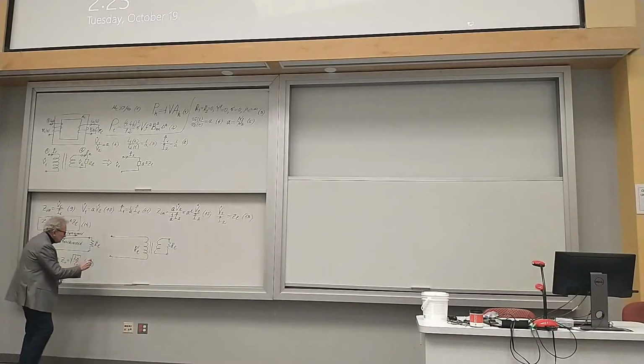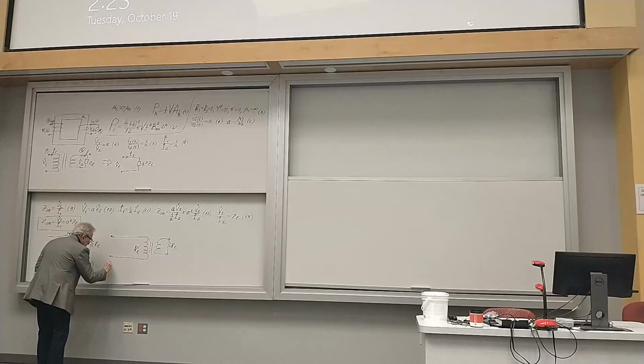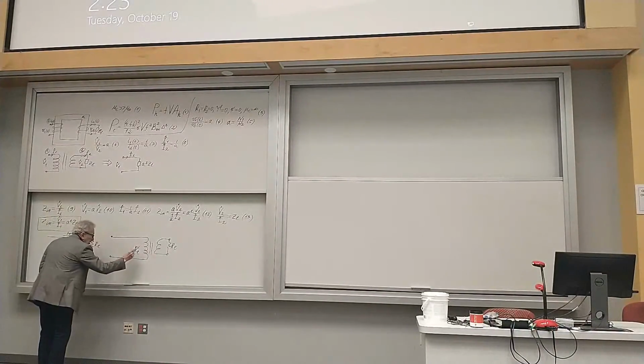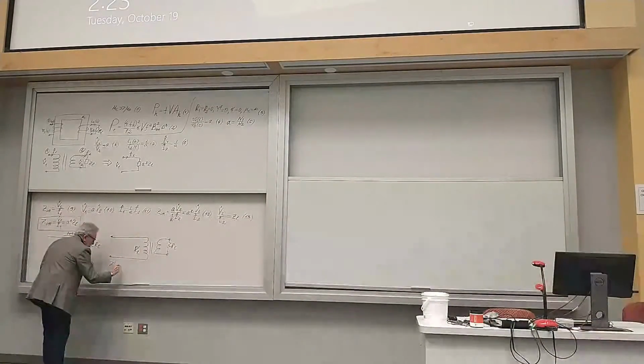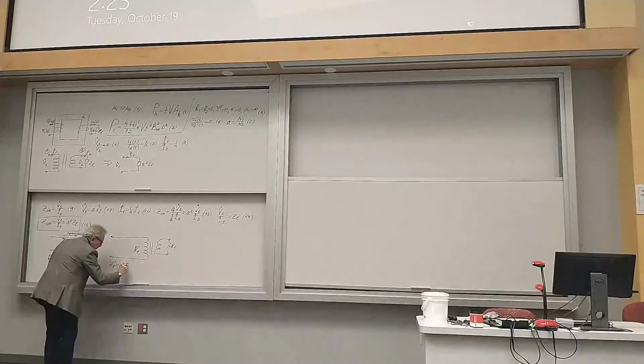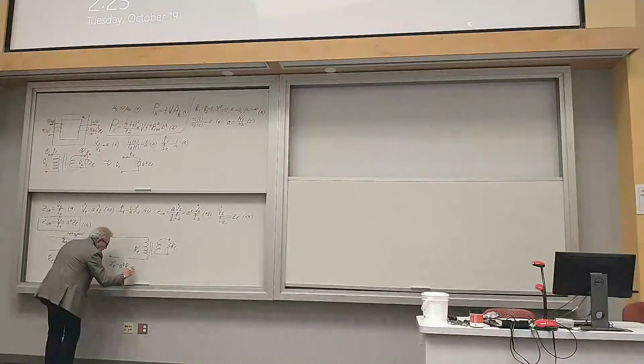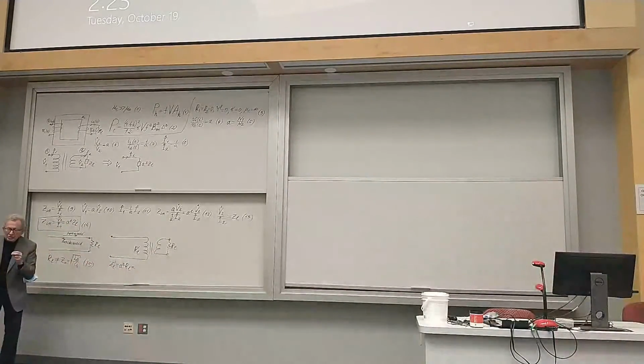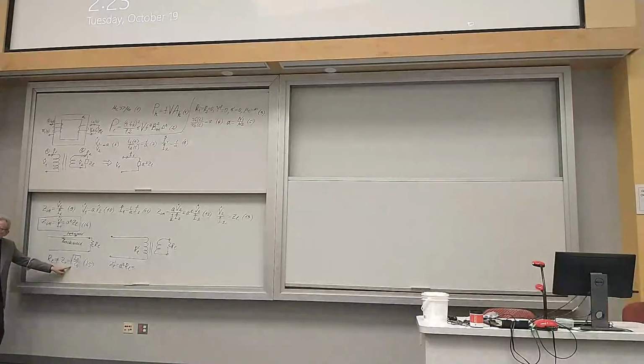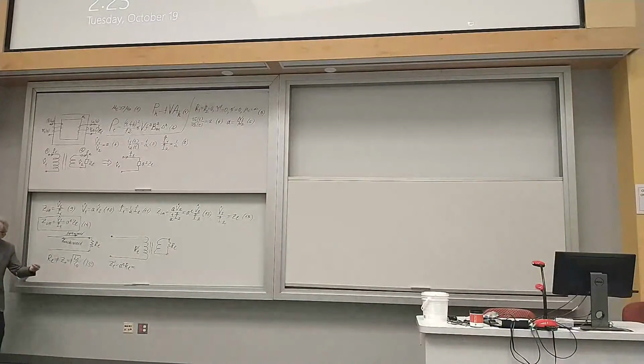And this impedance, Z_L prime, across these terminals, will be equal to A squared R sub L. Now you can choose the turns ratio A in such a way that it will be equal to the characteristic impedance. You have this freedom of choice.